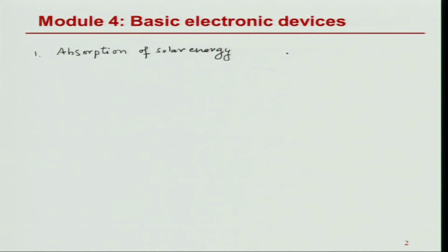And we have seen this earlier, that if I have a semiconductor, by virtue of its electronic structure, we can create an electron hole pair as long as the incoming energy that I am bringing is greater than the band gap of the semiconductor. So semiconductors by their material properties are amenable to absorb light which is greater than their band gap, and create an electron hole pair.